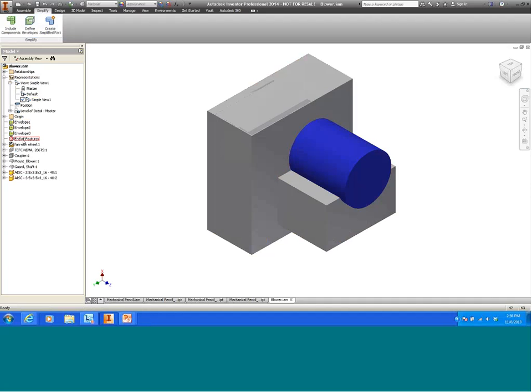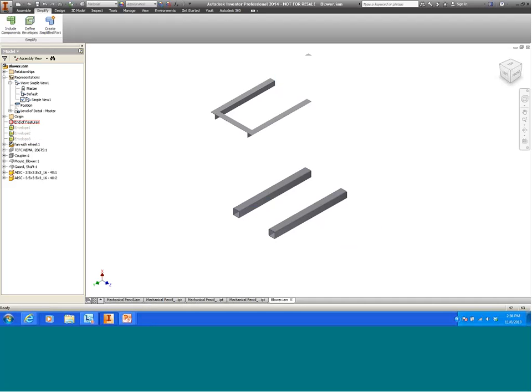I mentioned these are assembly level features, so they're always going to exist in the model unless they're suppressed. Just to show you, I can take this end of features marker and drag it back up to the top here. You can see that now my envelope 1, 2, and 3 have all been suppressed. And you can see that my simple view right now still has all of those framing components that I redefined and added to my simple view.